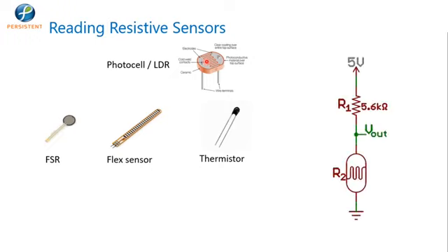So, if I go for a connection something like this, I will put one LDR component along with a resistor in series. This particular resistor value is constant, which will control the current flowing through it. But if I draw a voltage output in the middle of this series connection, this output voltage will vary whenever there is a change in the resistance value of this LDR. And when will the resistance of this particular component change? As per the change in the intensity of the light falling on it.